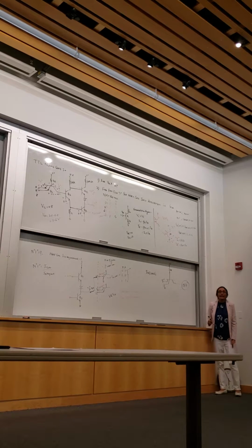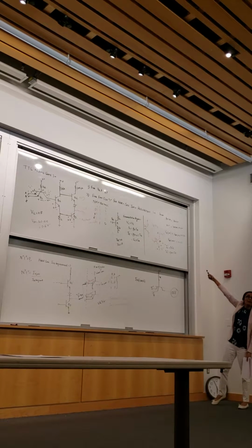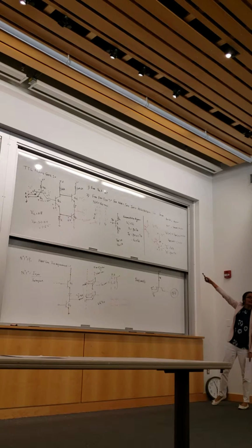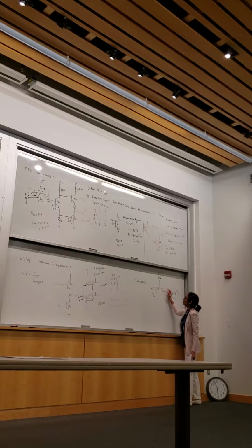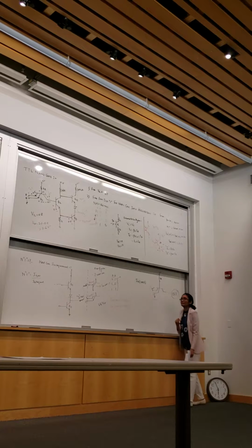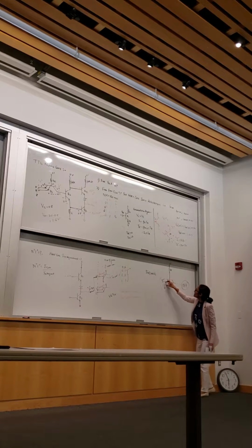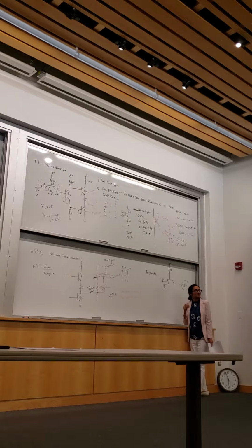Now you see in your given parameters there is one parameter named beta L. That's 1. Right? Now this guy over here, nothing is here, right? So you have this configuration. Now these 2 emitters are embedded in this one transistor. One is sitting at high, 5 volts, and another one is grounded. So it itself acts as a lateral transistor. I'm going to redraw this.